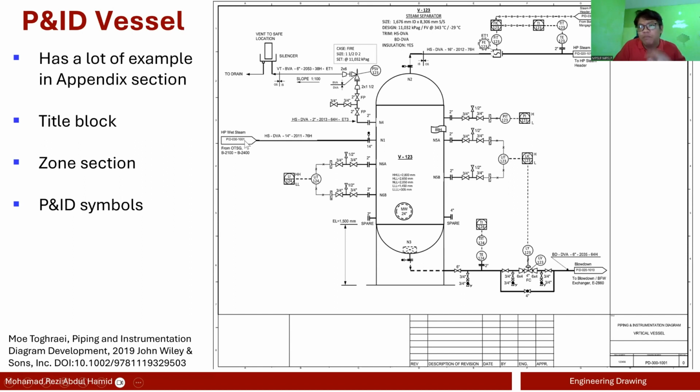But if you want to check the P&ID of the unit after or before that, they have different numbering as well. For example, here on the outlet, you have a PID 0201010. So if you want to see the P&ID of the high pressure steam header, you need to click this. It will redirect you to the next P&ID.